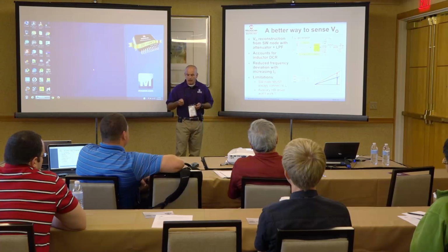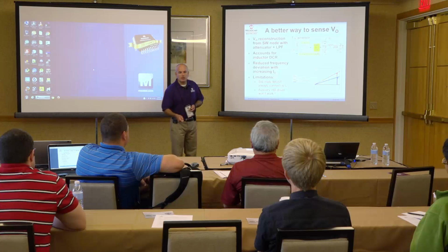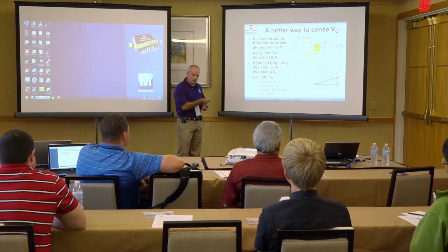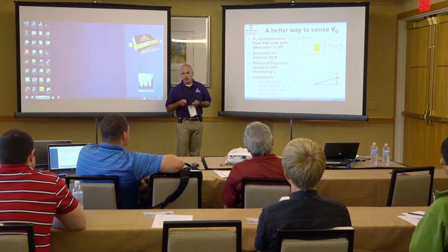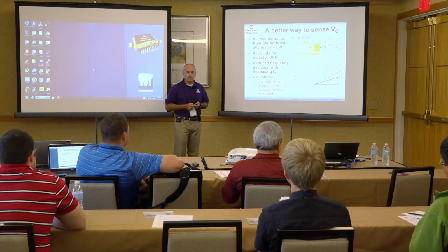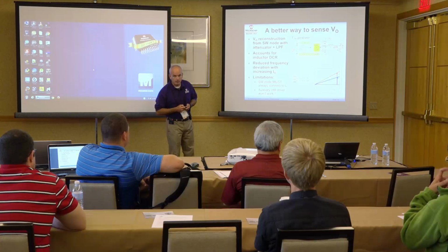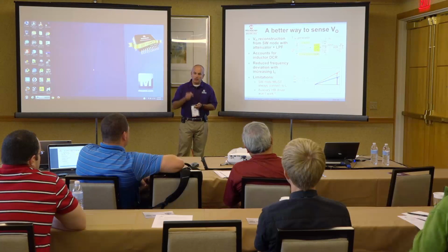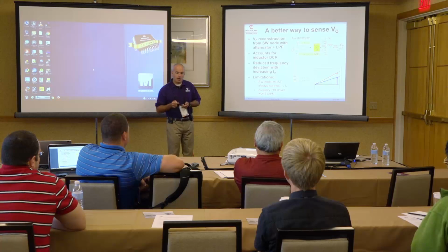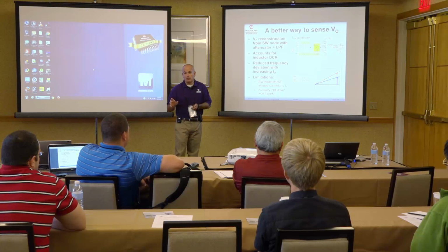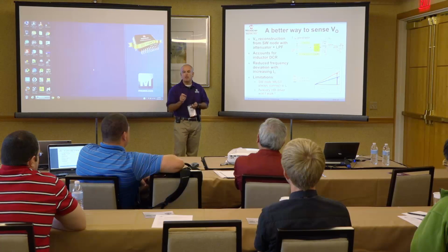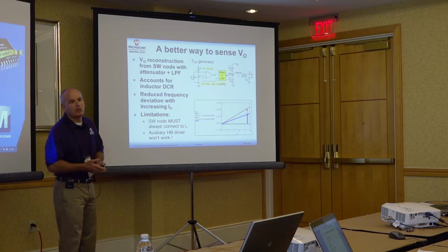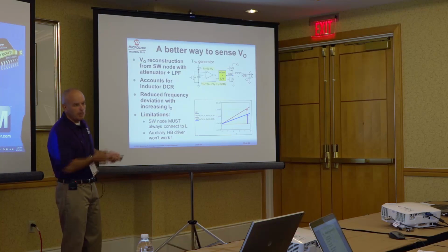So you may think, okay, I can ground the switch pin on the controller, use the high side output from the controller, connect it to the high side input of the driver, and use the controller that way. But you cannot, because what will happen is that the on-time generator will see an output voltage very close to 0. So the generation of the on-time will go basically to its minimum value, and the switching frequency will go to some crazy value. And I've been burnt by this problem myself.